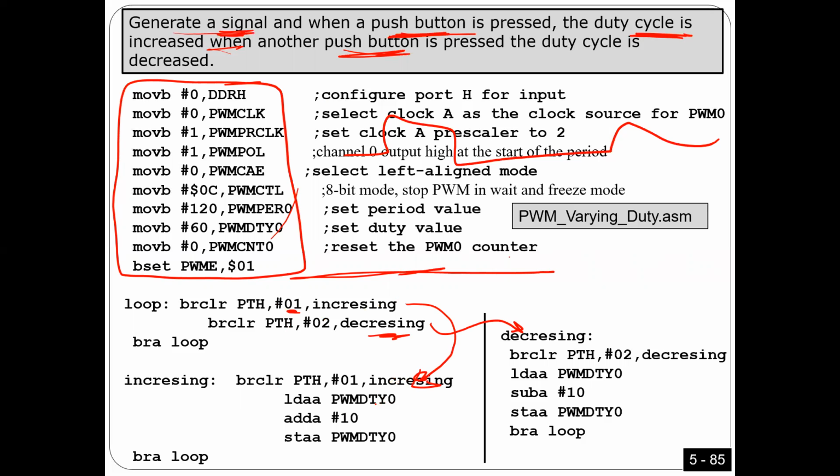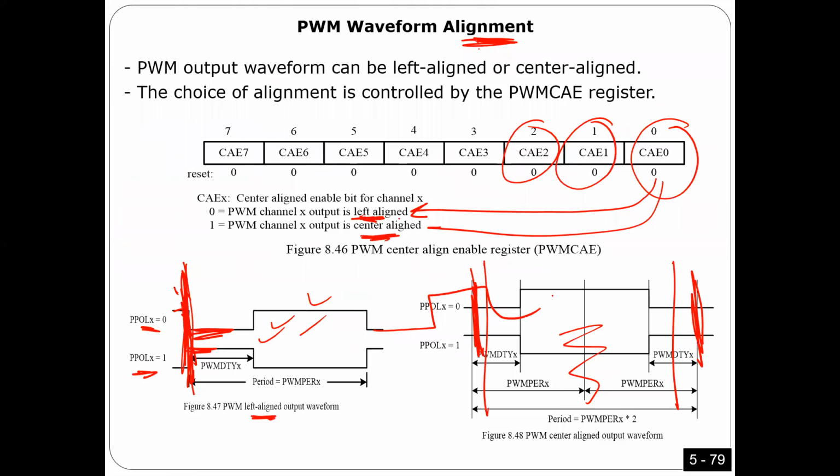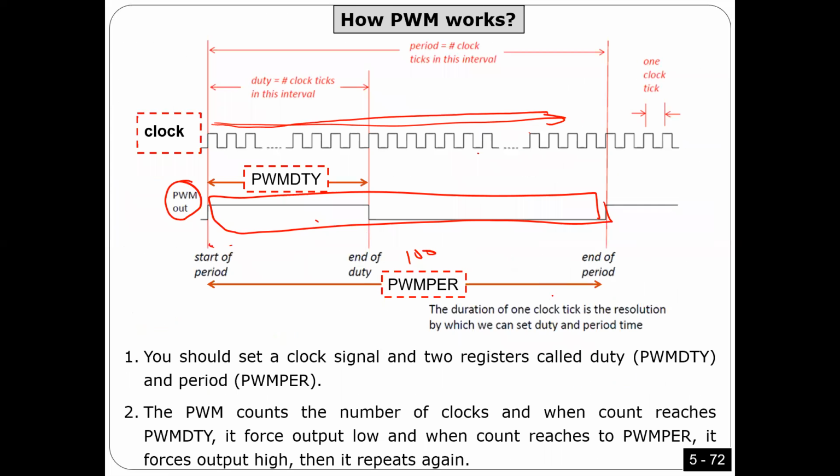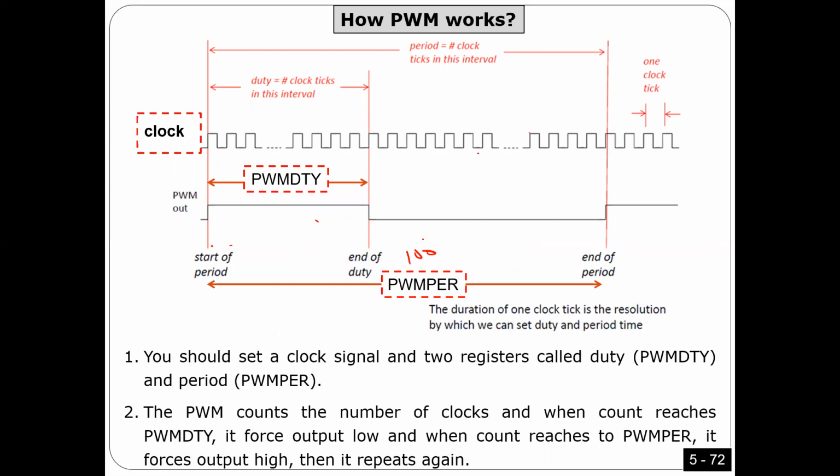So here, what I'm going to do, as you see here, guys, is say pulse width modulation duty 0, and then I'm gonna add 10 and return it back. So what I'm doing here is adding 10 to the duty cycle. Let me go back here to explain exactly what I'm saying. For example, if this one has to be 100, and I start with 20, I push a button, so I'm gonna make it 30 cycles. So I'm going to get it bigger, or I'm going to make it 40 or 50 or 60. You can make it bigger, or you can reduce it.